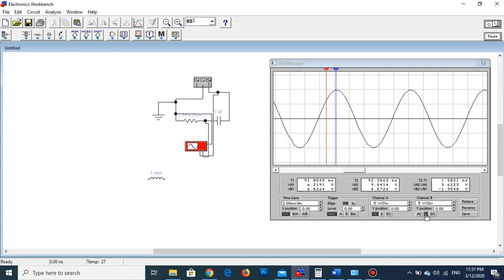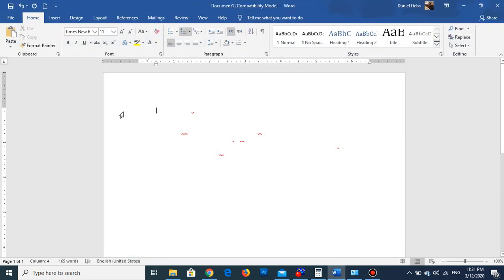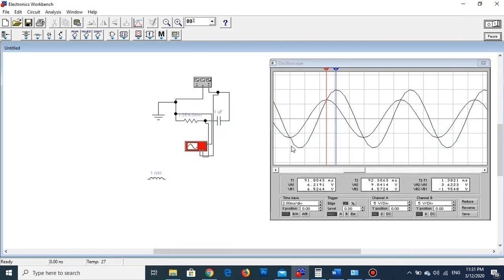So you know from 0 which one is the voltage of channel B, so it is the lower one. Thus you conclude that this one leads the other, so UR leads UG, or finally I leads UG. This is the important conclusion. Now I wrote these here, so first conclusion is UR leads UG, which implies I leads UG.